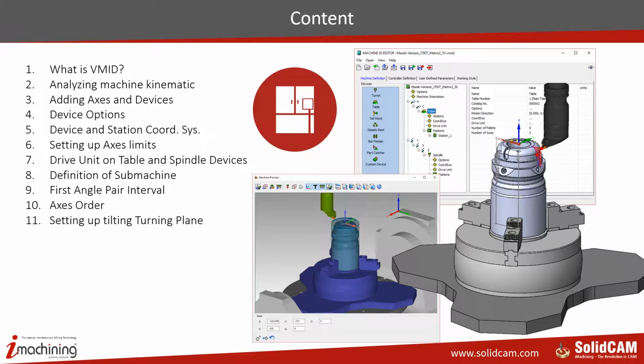Then we'll go towards how to set up the drive units on the table and the spindle, the definition of the submachine, how to set up the first angle pair interval and axis order, and the very last one and new parameter is how to define the tilting turning plane in the mill-turn module.